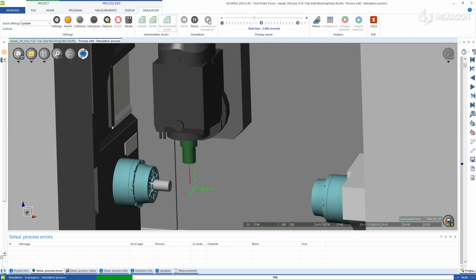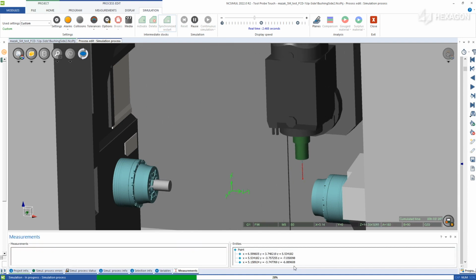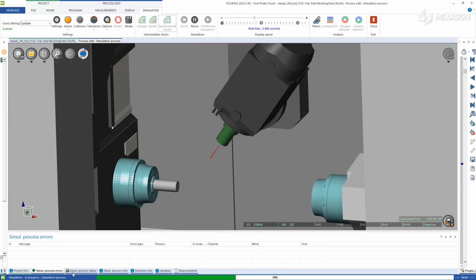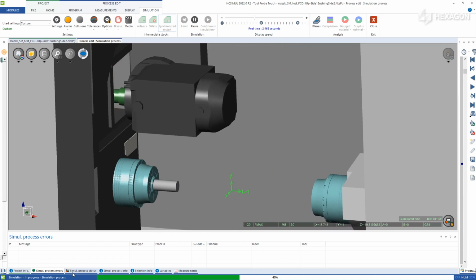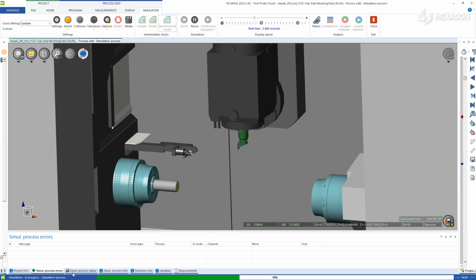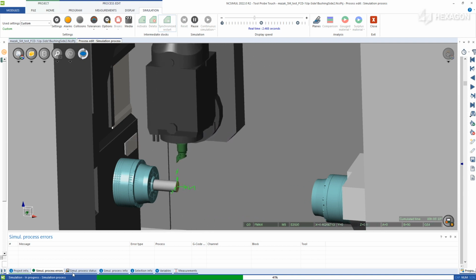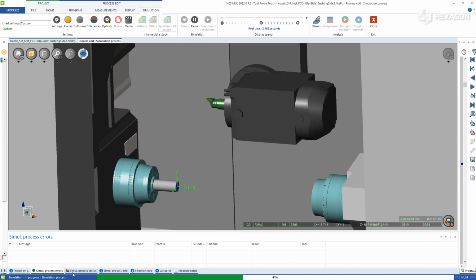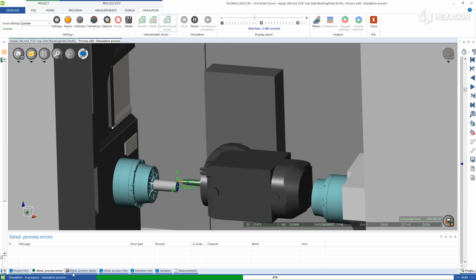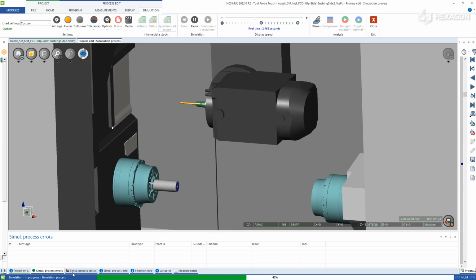In addition, the rough stock can be probed, the points recorded, and the program origin adjusted accordingly, just like at the real machine. This example also simulates the opening and closing of the tool change doors, as well as the extension and retraction of the tool probe touch-off. The different probing strategies allow you to measure any element placed in the digital twin in order to proceed with the macro logic. Renishaw and Blum are both supported, so you can guarantee that your machine is moving exactly like the real one will be, whether it's in-process dimension checking or even before the official program has begun.